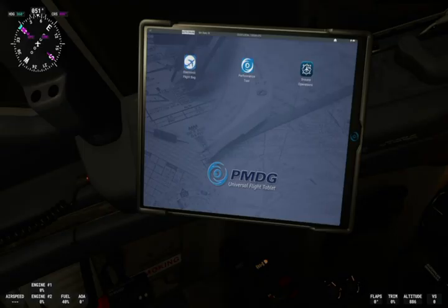So let's go to the FSFO first officer. Start the flow. Show checklist panel. Show performance data button opens performance. Start the flow and flow status grouping list of flight phases pane. Depart initial altitude. Departure flaps combo box 1. Departure runway combo box 23L, collapse, select departure runway 23 left, that's what we want. V1, VR, V2, clean speed, cost index edit, enter cost index 5, assume temperature edit, enter assume temperature.